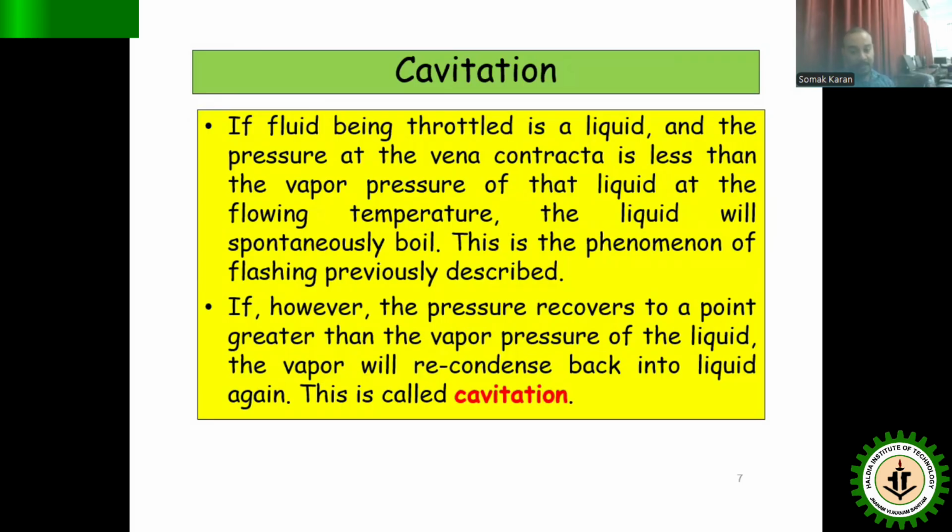That's why I am saying that cavitation is the effect, and flashing is the cause. Whenever flashing has occurred, the liquid starts boiling, and if the liquid starts boiling, there will be a condition of recondensing of the vapor back to liquid, and this recondensing is nothing but cavitation.